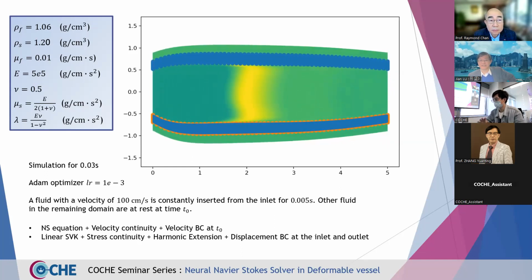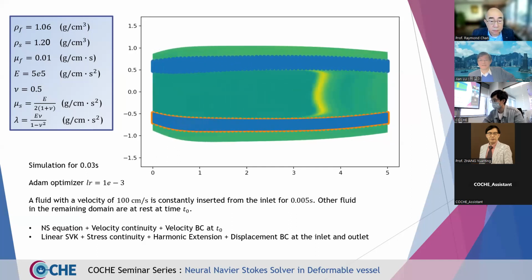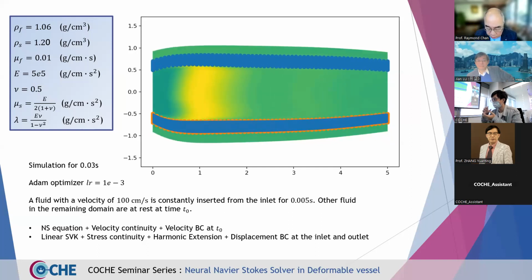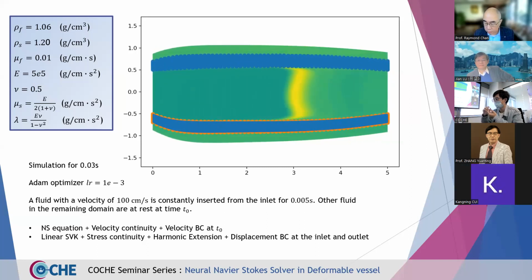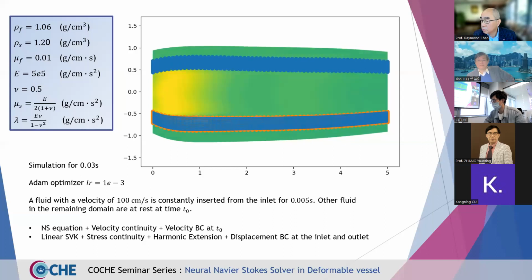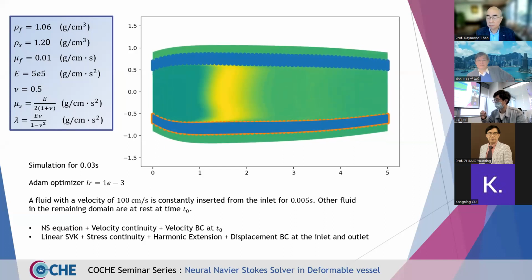In our future work, because you can see at this moment we have only one layer, the stress in the layer is uniform. This is our assumption at this stage. But in the future, we'll add more layers, because I know that the different layers of the vessel wall are composed of different components. They have different elasticity properties, different Young's modulus, different Poisson ratio, or some other complex physical properties. Of course, in our later stage, we will take this into account so that it should be a more realistic system.